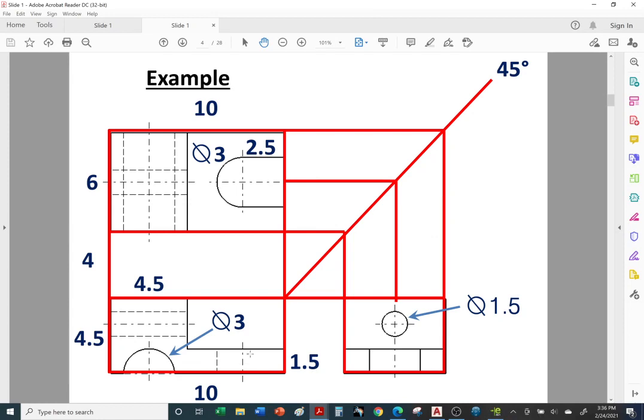All right, so I'm going to set up the AutoCAD file for you. And you're going to see what's referred to as construction lines. Here I'm showing them as red. In the AutoCAD file, I think I'm going to use magenta for our construction lines. Construction lines are temporary lines to guide you along to create the drawing. Okay, so we're going to be creating a rectangle for the front view, top view, and side view. So for the first few chapters in AutoCAD, I'm going to be creating this for you. Eventually, you'll be creating your own construction lines.